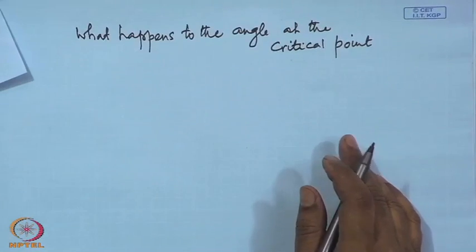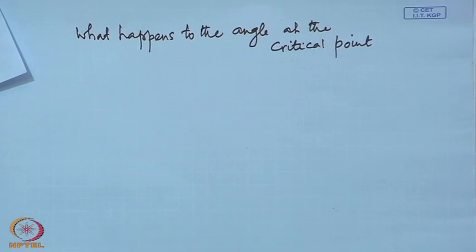So, if all the points on the circle are regular points of the transformation that we would like to use, then the resulting geometry will also be smooth everywhere, but we know airfoils are not smooth. Airfoils usually have a sharp trailing edge. So, of course, with a fully analytic function or fully regular transformation we will not get an airfoil. So, we need these types of critical points within our transformation. That is why the critical points are very important and we must know what happens to the angle at the critical points.